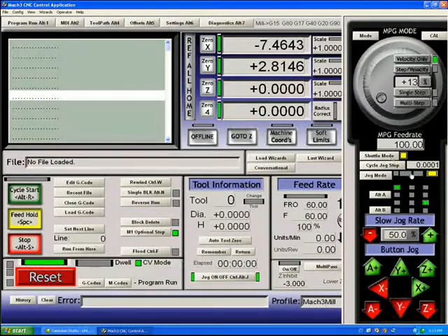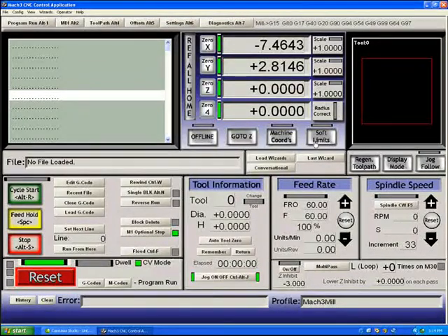You'll notice when I selected shuttle mode, our jog mode went over to MPG mode. Turning off jog mode and we'll go back to the normal jog. So if you look at this screen, the second LED here should be lit, indicating that you're in normal keyboard jog mode, and you should have a jog speed above 5%, and you should see movement. Hitting the tab key will make that jog screen leave the screen.